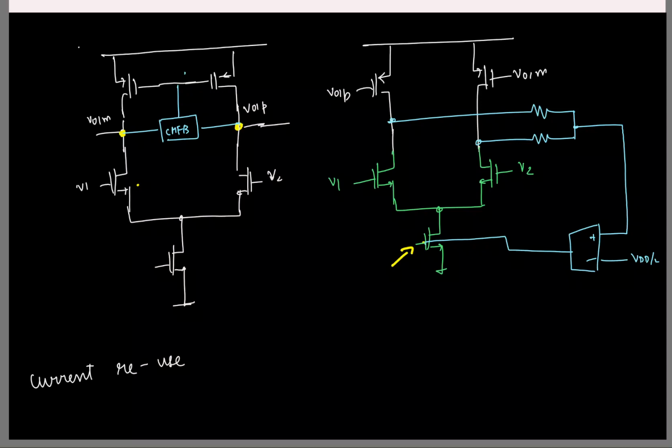This is for the common mode half circuit. Let's say this is the first stage. It connects to the second stage here. And where is the output taken from? From here. That's where the feedback is complete. So I'll have to connect my capacitor between this input and this output. Okay, so you'll have to go and put a capacitor like this. I have two outputs here, so I have to do it like this.